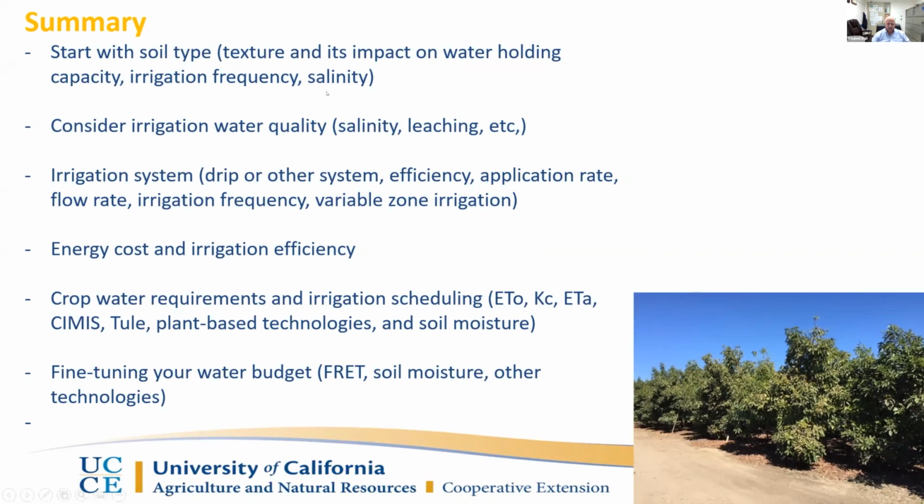If you have lighter soils and you have a little bit of over irrigation, salinity may not be a factor. But if you have a heavier soil and you always have ET, evapotranspiration, going on, and the salinity is left behind, we need to do leaching once in a while.